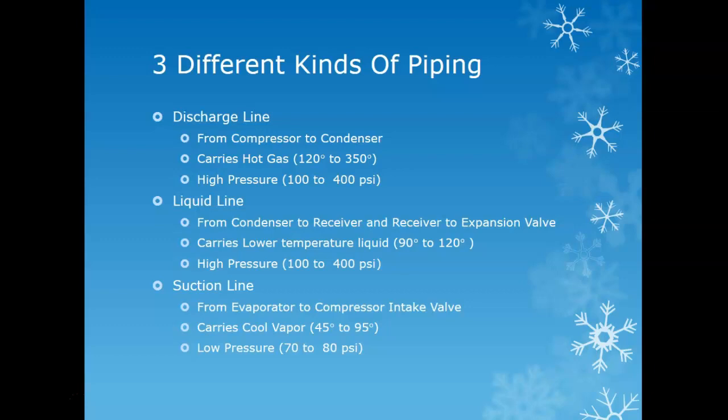Yeah, it'll do that too. One of the typical things that you see a lot in manufacturing is something kind of like that, where you wrap something around it and see if it picks a hole in it. They also can have giant tubs of water where they'll submerge things, and what they're looking for is bubbles rushing out of any place where they're trying to test for air.